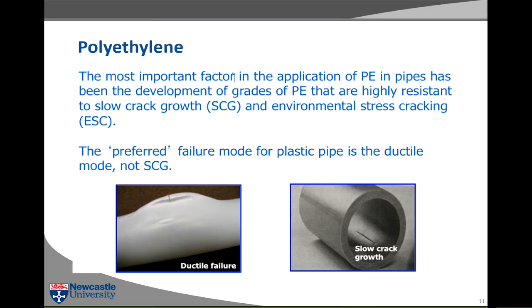Just as in a tensile test, the material will start to neck down in one place, and it will become thinner. And the place where it necks down, of course, will be weaker, so it will start to bulge. So you'll start to get a bulge in the pipe. And the material will be thinner. So it's just like the neck down region in the tensile test.